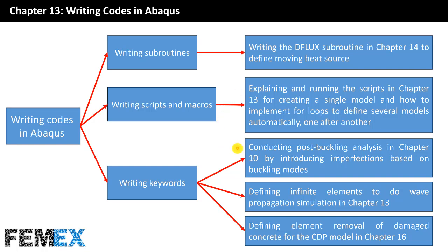And about writing keywords, I have conducted post-buckling analysis in chapter 10 by introducing imperfections based on buckling modes, and also I have defined infinite elements to do wave propagation simulation in chapter 13, and finally I have defined element removal of damaged concrete for the CTP model in chapter 16.